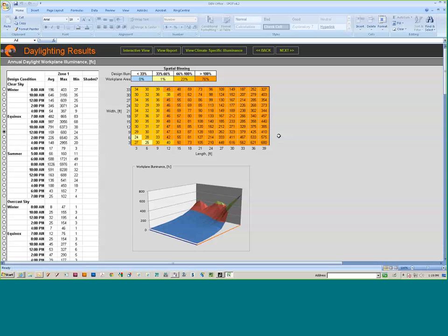So again, we'll have to do this as an iterative design process, going back and forth, changing one thing at a time. And the other thing you had was an 88% visible light transmittance glass. You could cut that down a little bit, but that's a problem because if you cut the amount of light coming through the window, then penetration will become a problem. You won't have as much light penetrating all the way to 12 feet on the west side if you cut down the visible light transmittance. So it's a balance going back and forth.